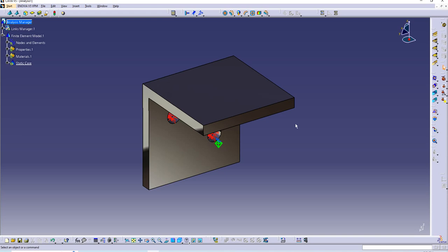You need this boundary condition to solve the equation: when x equals something, what is y, or when y equals 0, what is x. So that is the boundary condition. By assigning the clamp here, we are actually giving the equation what it needs to be solved properly.